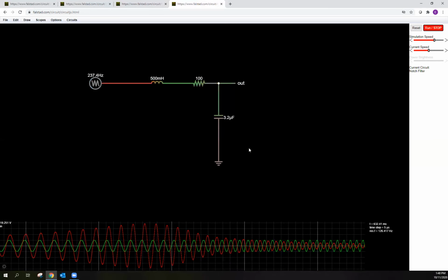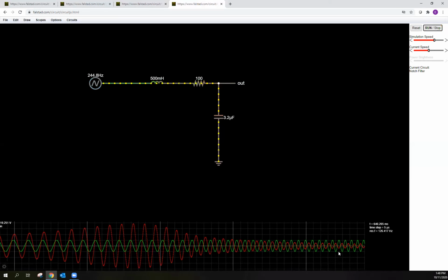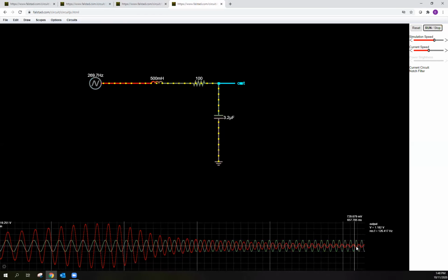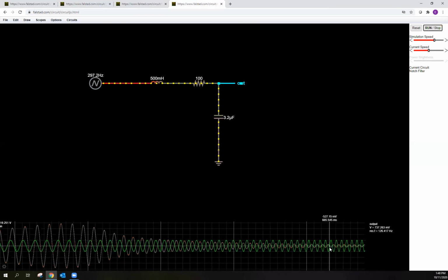Look, I'm going to pause it here. Look at this resonant frequency. The peak is happening at the 0. So we're a quarter cycle out of phase. And the peak is crazy high relative to this one. As we keep increasing the frequency of the input even more, now look what happens. The amplitude, sure, it drops off. The red gets smaller and smaller, but look at the phase. The phase of the output is now closer and closer to 180 degrees out of phase, completely out of sync with the input. And so we keep running this more and more. Look, it's falling off, right? And hopefully this makes sense.